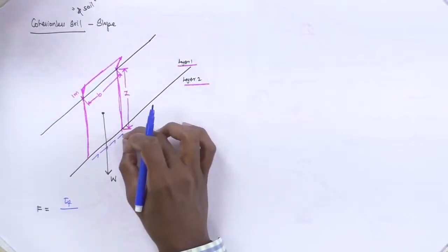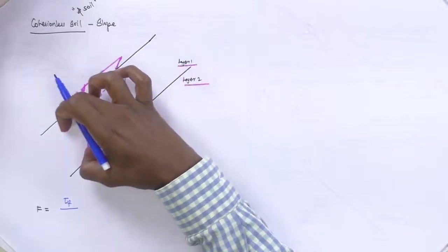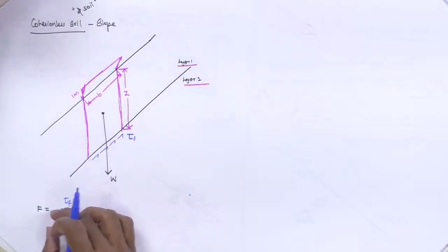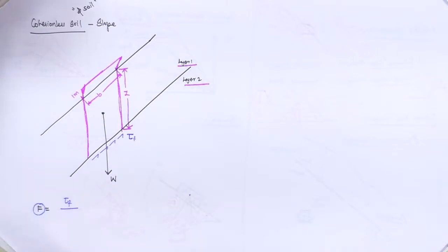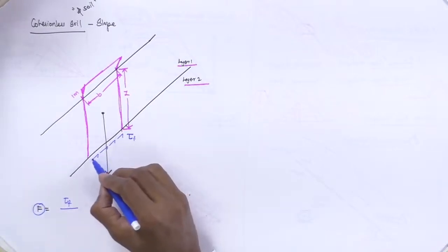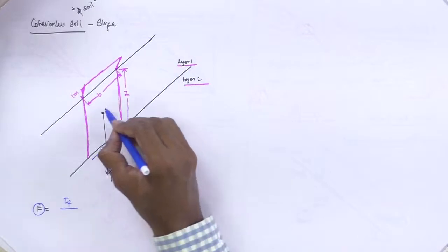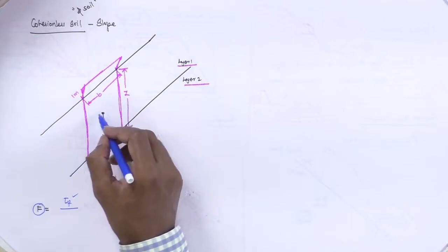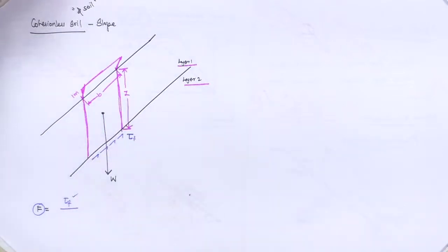So this is an available strength. So what is this sliding stress? That has to be put into the denominator. By the way, we can get the factor of safety. So this is going to favor us and this is going to be against us. The term in our favor goes in the numerator, and the denominator is going to be the sliding force.